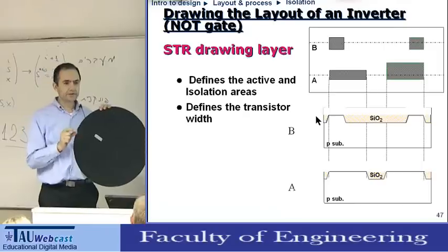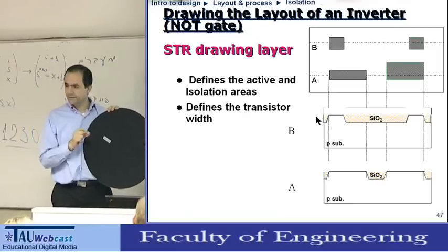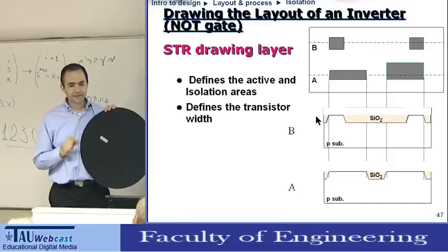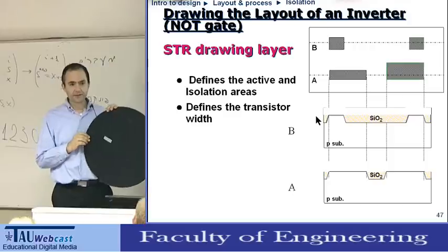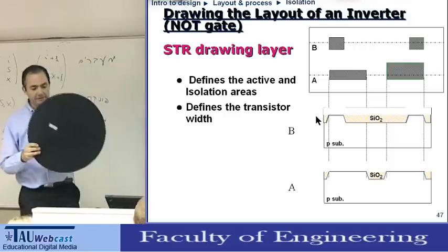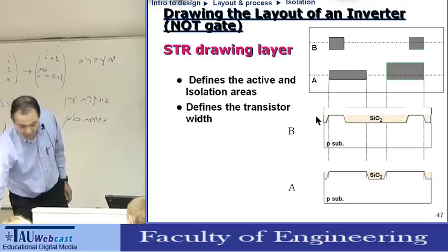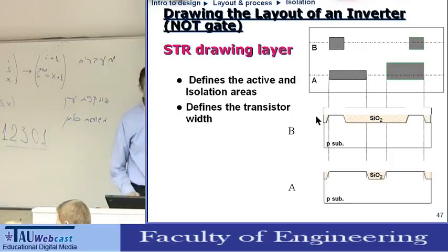But we can also determine from the phase what is the thickness of the remaining layer. So we can actually polish and know before we endpoint if we're getting close to endpoint. So this is a real pad and a real window. The laser used is different.